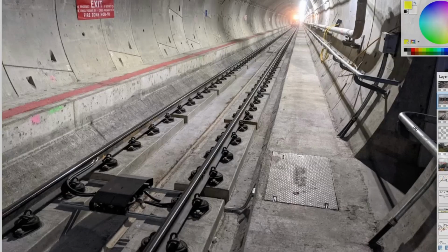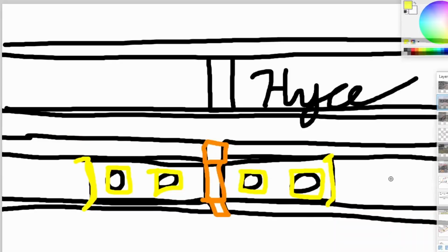And as well, in some applications, we also have rail clips instead of spikes, depending on the kind of railroad we have, because some ties and some applications use concrete rather than the wooden ties. When you have rails, you need to join them together. And back in the day, we had joint bars that had holes in them and rails that had holes in them that we would stuff bolts through and hold things together.